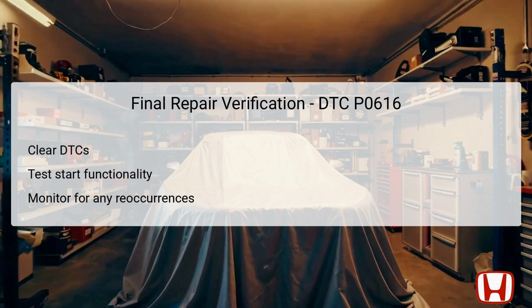Upon completing repairs associated with DTC P0616, the final repair verification step is crucial for ensuring that the issue has been resolved. Start by clearing the stored diagnostic trouble codes, DTCs, from the PCM to reset the system. Once cleared, test the vehicle's starting functionality to confirm that the engine starts smoothly without any hindrance.